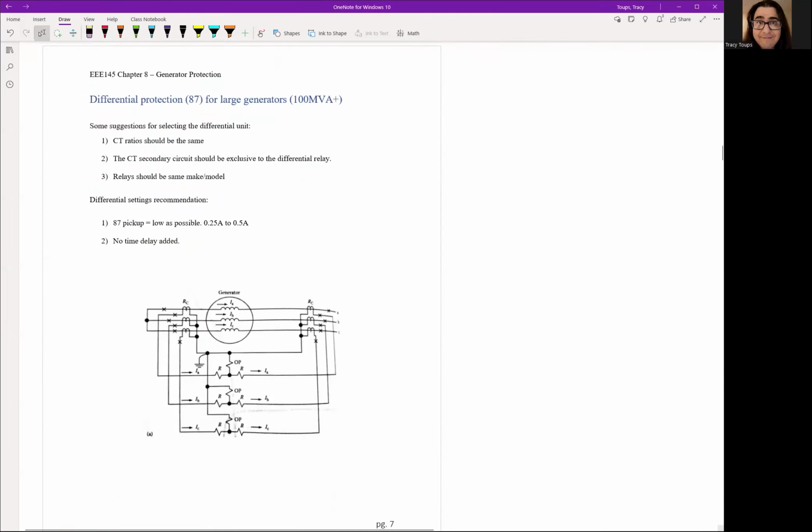Now let's go on to the bigger standard one you're going to see. You'll see a large generator. You see you have 3 windings. Again, on A phase, you always have your positive terminal of the generator and negative terminal of the generator. So remember, for any generator, you have 6 wires. You always have A, B, C positive going out, typically capital letters.